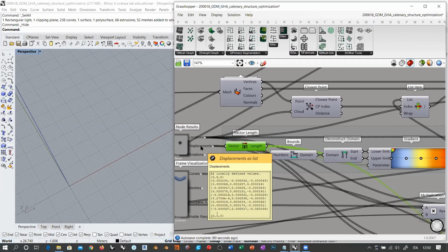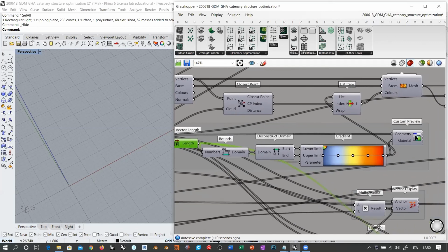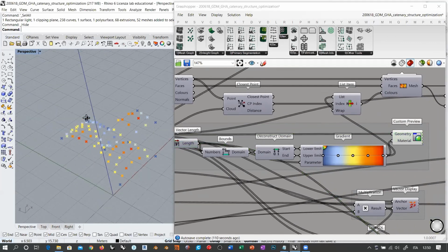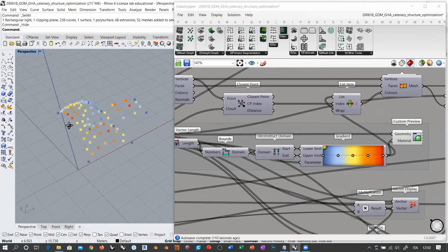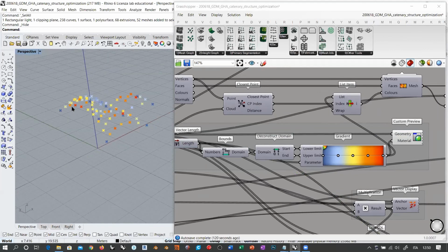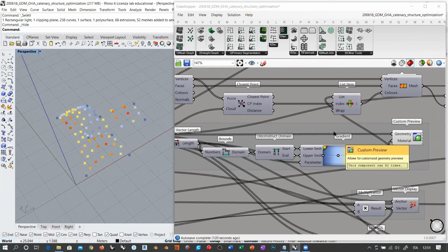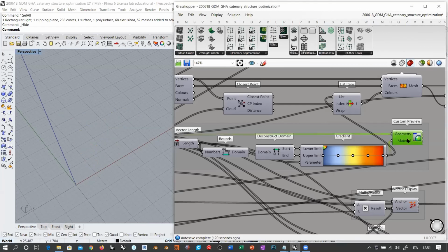These are the 3 spatial components of the displacement vector. So I take the length of the vector, which is the amount of displacement that you have per node, and then remap it in order to visually see what are the nodes or the parts of this mesh where you get the highest deflection, or deformation. So these are the areas inside this mesh.